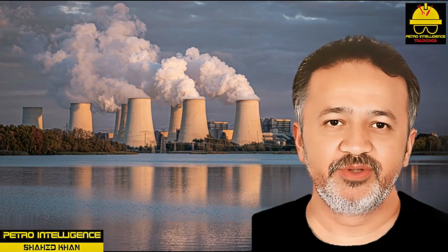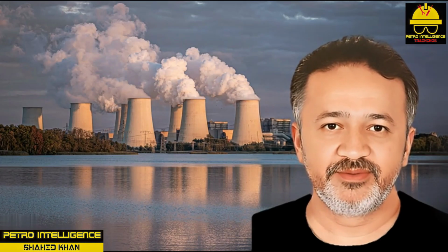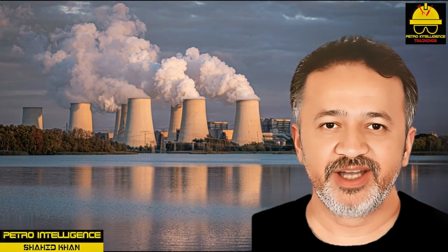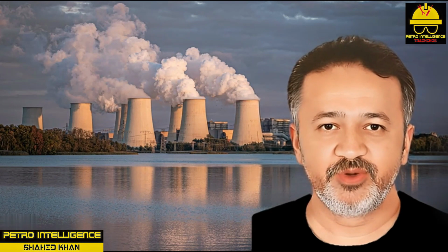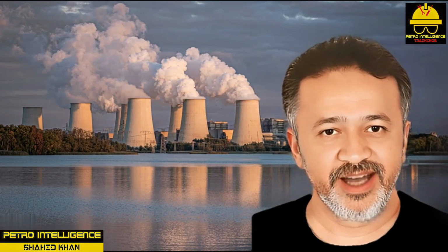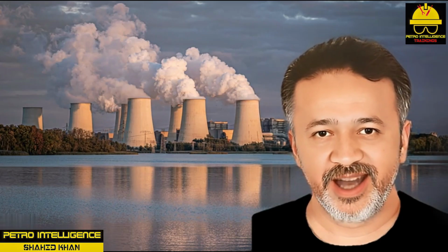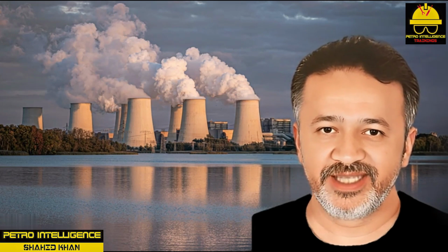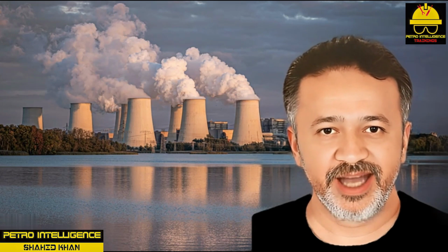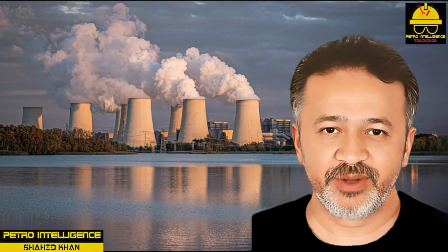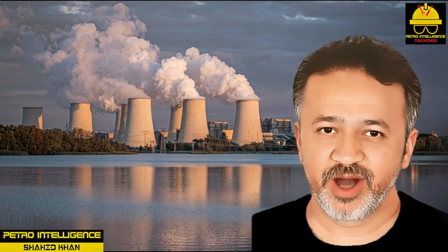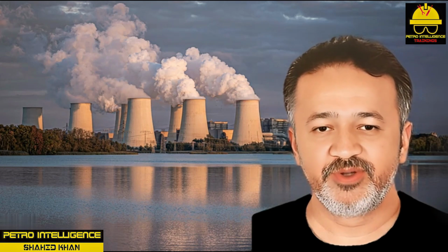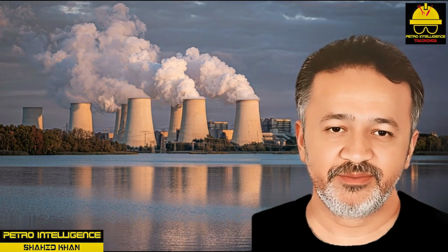Forced draft cooling towers produce airflow mechanically through the use of fans located on the lower side of the tower. The fans push air into the tower. Induced draft towers have a fan on top of the tower. The fan pulls hot air out of the top of the tower. Water cooling systems use heat exchangers and cooling towers in combination. Cool water is pumped from the tower to a heat exchanger, where hot process fluid transfers heat to the cool water. The hot water is returned to the tower to be cooled.